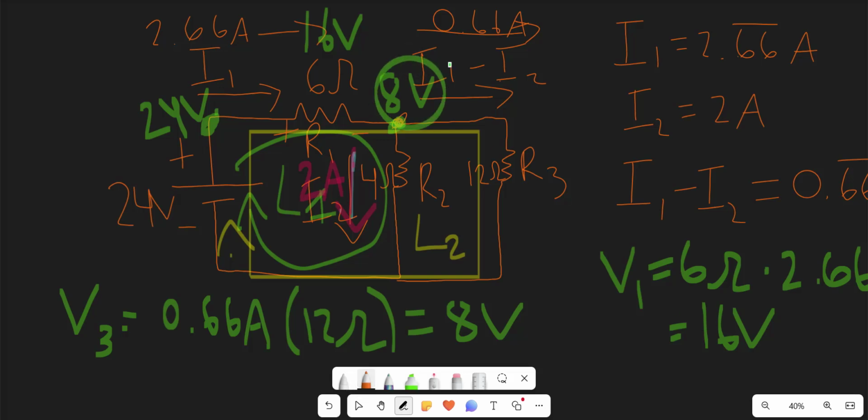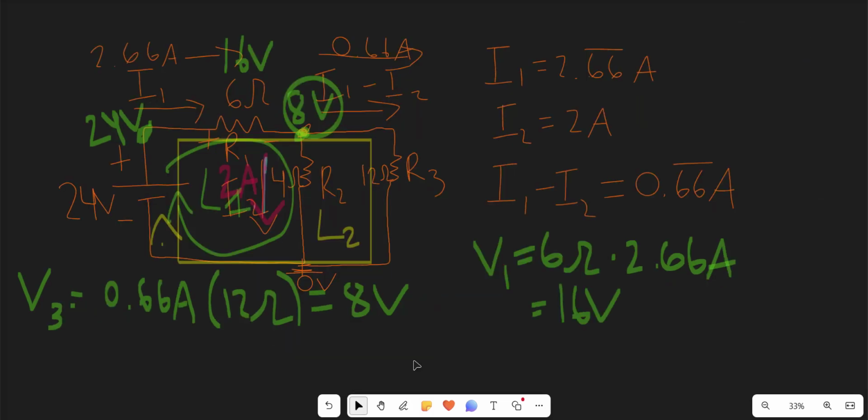And the way you can tell our answer is correct or not is pretty simple. So in most circuits that you come across, there will be something called ground. So that's just going to be this point right here. And pretty much at this point, the electric potential is always going to be 0 volts. So this explains why current flows from this node down this path and then towards ground, because it's at a lower potential. And we are done.